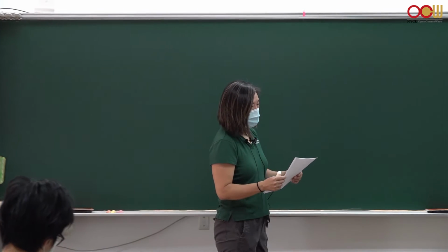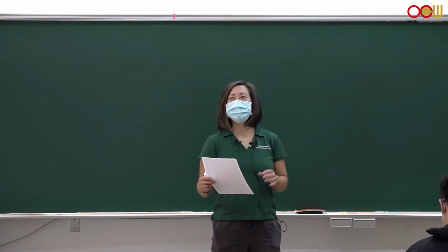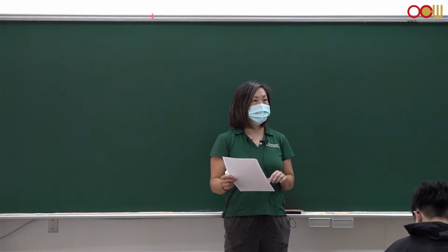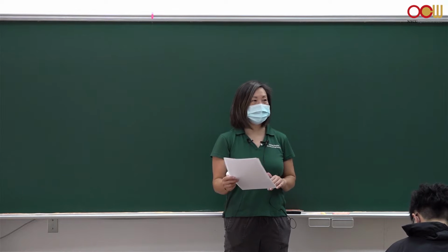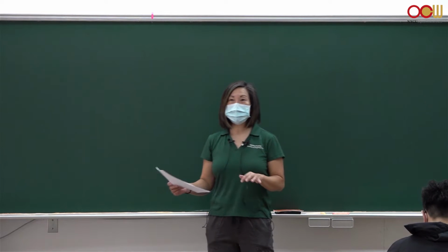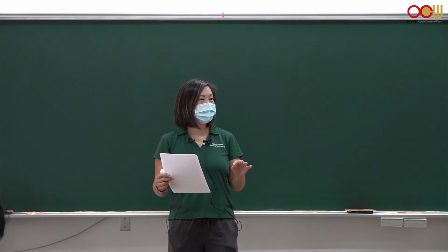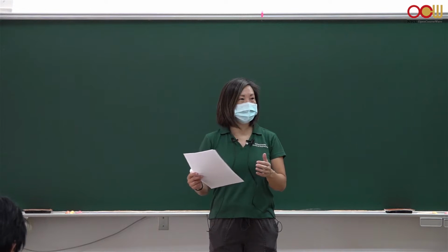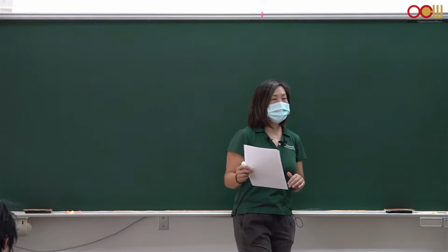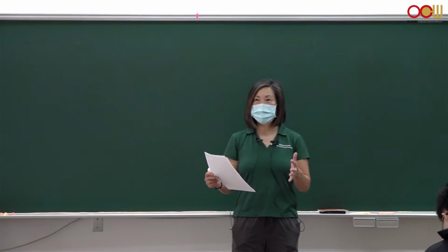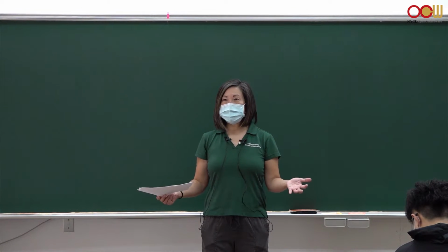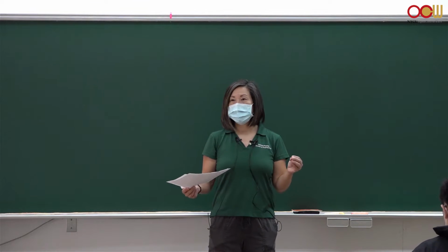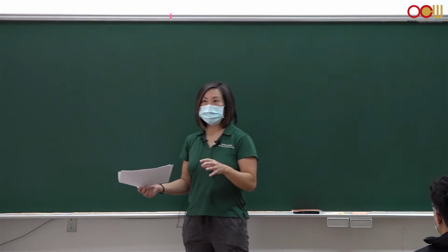So last week, we talked about cracks. We talked about failure and how cracks contribute to failure, and that cracks are a source of all the different kinds of failures that you see in materials. Every time you see a material break, it is because a crack has started and has grown all the way across the material. Okay? So whenever we want to talk about fracture toughness, how strong a material is against breaking, we are talking about either preventing crack growth, getting rid of cracks, or minimizing cracks.